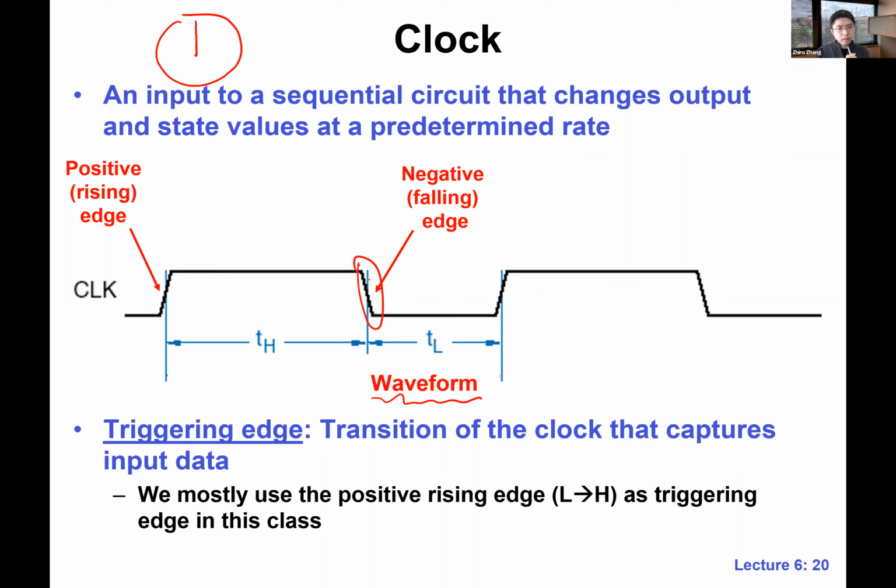I cannot guarantee that in all cases, but in most cases in this lecture and in class, we'll be focusing on the rising edge, going from 0 to 1. And the moment we have an edge, it's called a clock tick. Basically, the clock ticks the moment we have a triggering edge. This is the very basic concept of a digital binary clock: 0, 1, just oscillate.